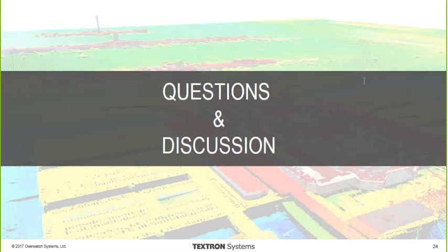Let's see, what type of vegetation, tree canopy, extract tools are available? The tree extraction tool in LiDAR Analyst is similar to the building extraction tool. You hit the button, it comes up with just a few parameters for the input data. And so what it does is it extracts tree points. The tree points are going to have your typical attributes, height, min, max, average height, things like that. But also it's going to have stem width and canopy width and things like that.